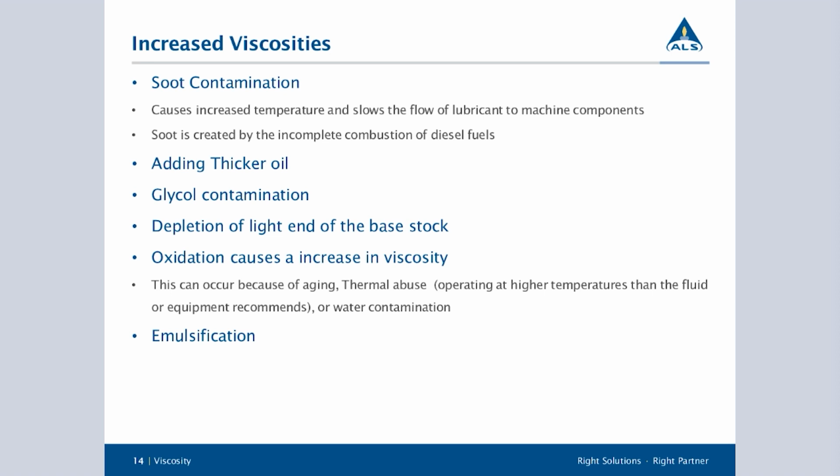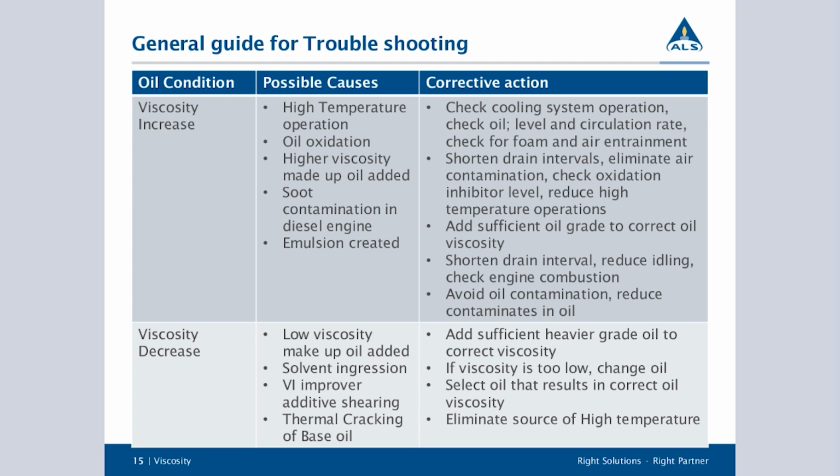So I took all of that, and this is a chart some of you might have seen before, maybe not. We put it into just a common chart, our general guide for troubleshooting. So this is why your viscosity is increasing or decreasing. Please definitely refer back to this a few times. I had a few of our diags look this over with me in terms of what recommended corrective actions are. And so we're just going to look over those recommended corrective actions.